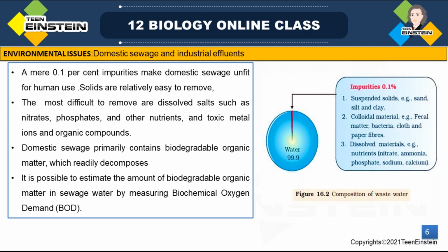And how can we estimate the amount of biodegradable organic matter in sewage water? We can measure the biochemical oxygen demand, BOD. Through that, we can estimate the biodegradable organic matter in sewage water.